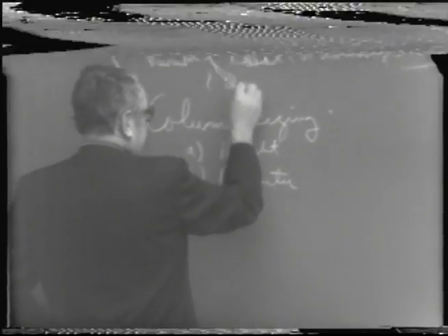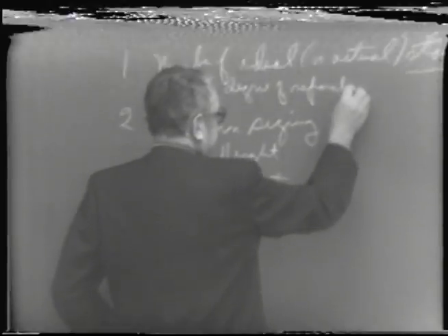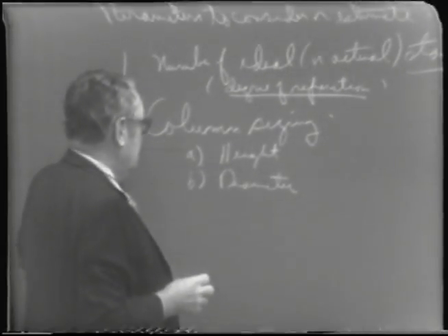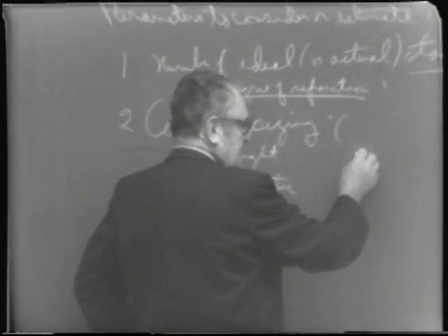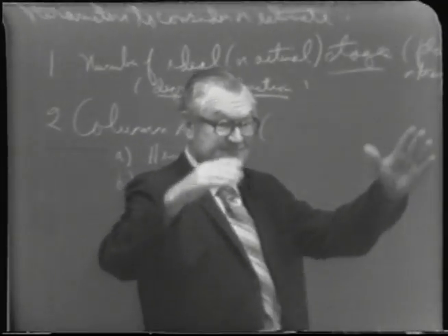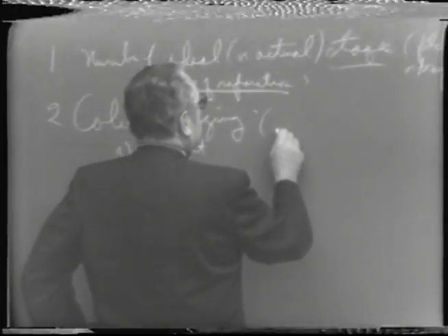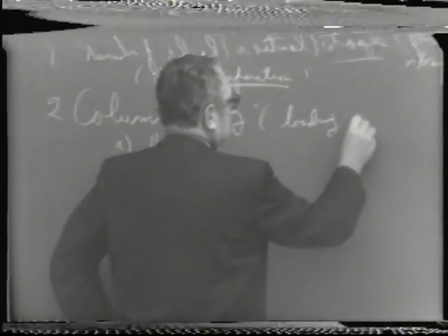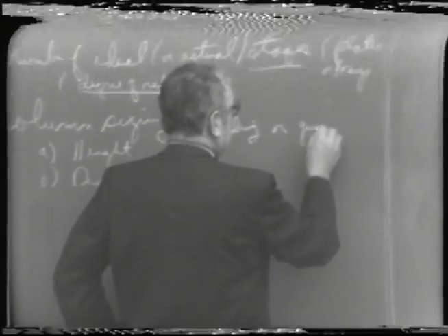As I'll put down here, degree of separation is the primary consideration here in the number of trays. Column sizing here is primarily concerned with the loading, or the throughput, or how much you're going to produce. Has to do with the loading or quantity of product.